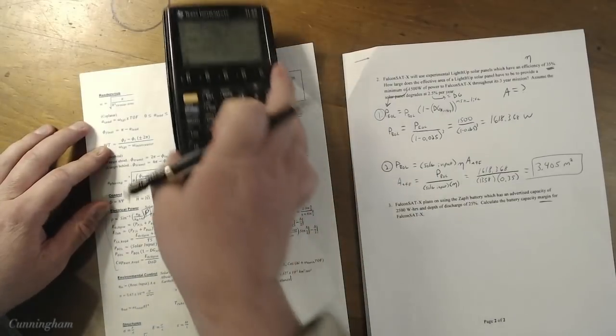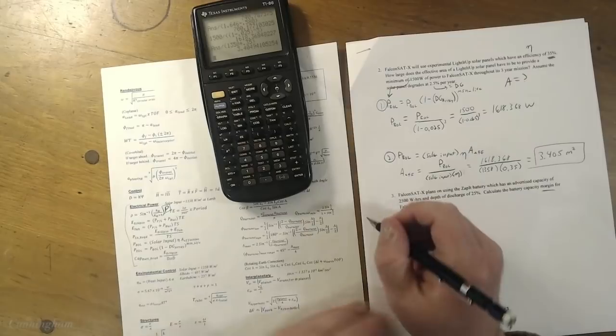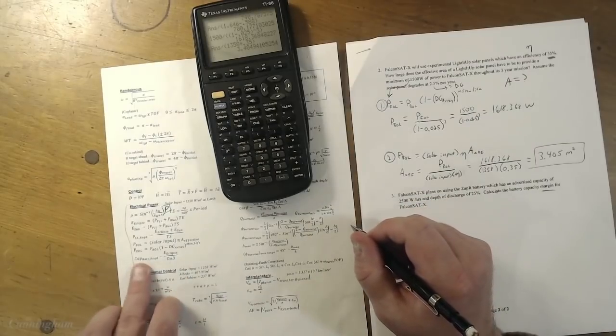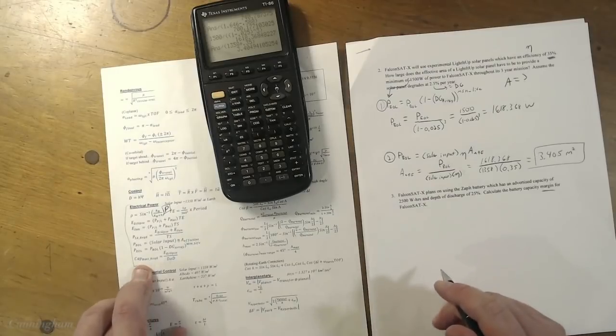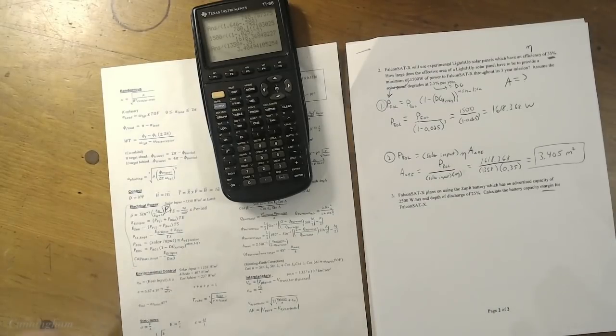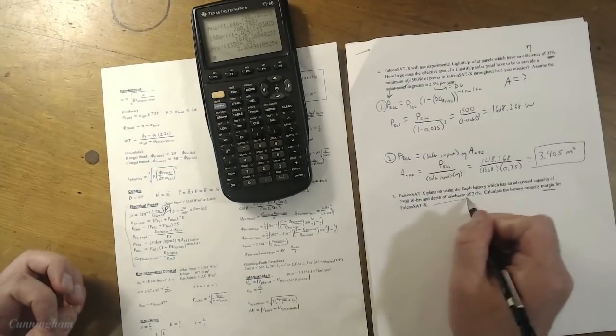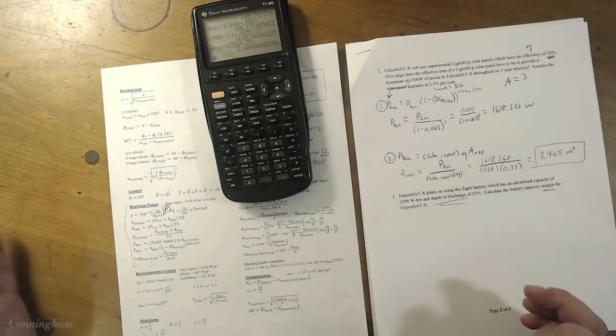Okay. Well, we only have one equation we really have to use for this, which is nice, and it's right here, the capacity of the battery that we need. How big a battery? That's the question. How big a battery do we need so that we can only use 25% of it in eclipse and then just charge up that 25% when we come out of eclipse? So depth of discharge is how much of the battery you use. Basically, you only want to discharge 25% of it. Let me put it this way.